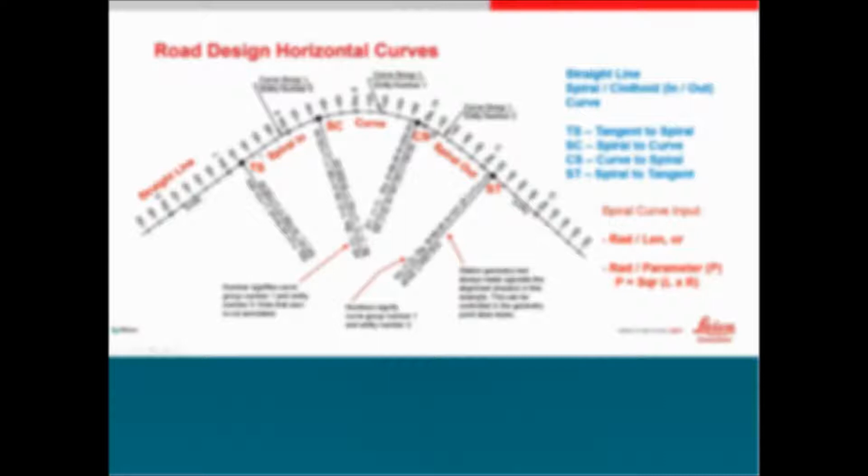Thank you very much. Okay, in some applications of surveying software, you may need to input parameters. For our modern Leica software now, we just need to input the radius and the length for a spiral curve. But in some old applications, you may need to input parameters which you can calculate using certain formulas. This one we will come to in future, but I have it in the PowerPoint and I will share it with you all.